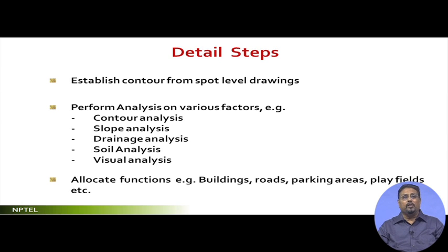First step is that you establish contour from the spot level drawing. Now, this is the first step of the landform design, which you are not doing at the design stage. If you recall, when I was saying that when you start doing your site analysis and investigation, 50% of your design decisions are taken there. So, establishing contour from the spot level drawings is the first step of the landform work.